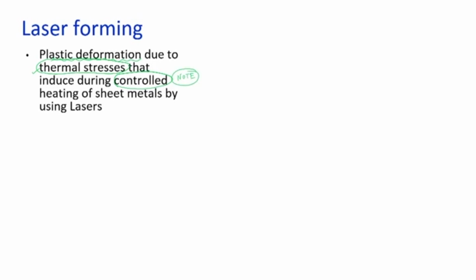If the energy is more, then the material will get ablated, and there would be cutting instead of deformation. During the experiments we can easily notice that if there is an increase in laser power, an increase in heat input, the material will start melting. There is a phase transformation from solid to liquid.